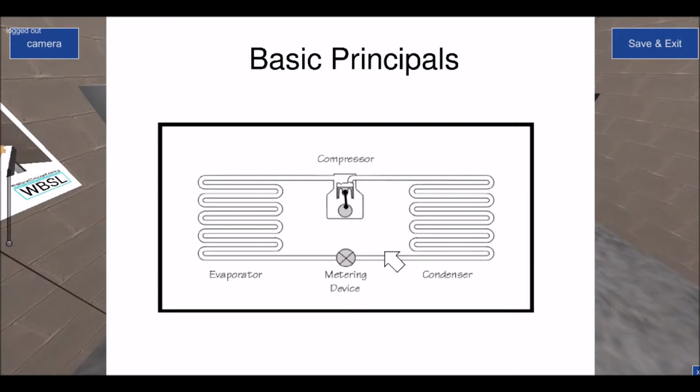It enters into what we refer to as the liquid line, the pipe that connects the condenser to your metering device. On a refrigeration plant or system, there will be additional accessories added, such as a dryer, a filter dryer, and a sight glass. They're the minimum. Then there can often be other accessories, but we just won't go there for the moment. But the liquid line carries the high pressure, high temperature subcooled liquid as far as the metering device.